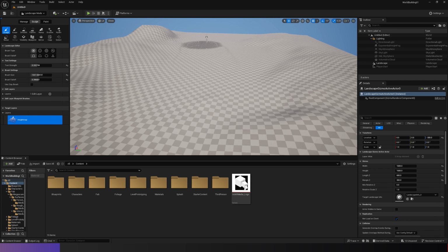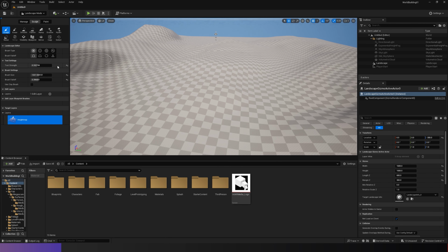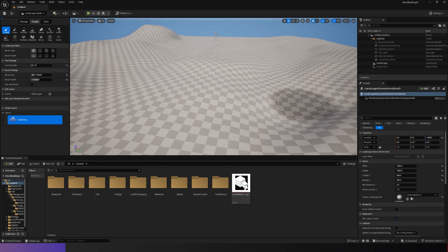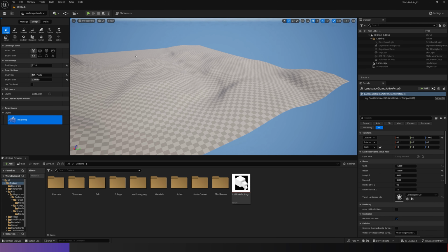Now, what you'd want to realistically do is think about what this kind of land would represent. How flat would you want it to be? Would you want any kind of paths or lakes in the way? So I'm going to just carve in to our land a little bit by holding Shift and left mouse button, and just bring my brush size down a bit so I can start sculpting out this kind of ditch through my landscape. And again, the longer I hold my brush over the area, the more it'll just keep carving in or adding to my selection. And that will do for now.